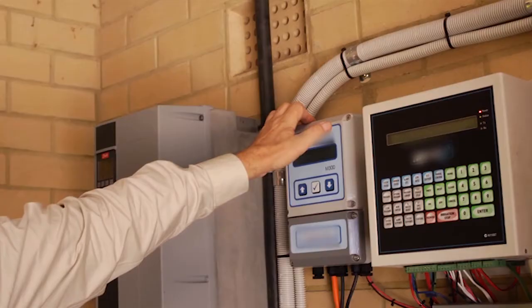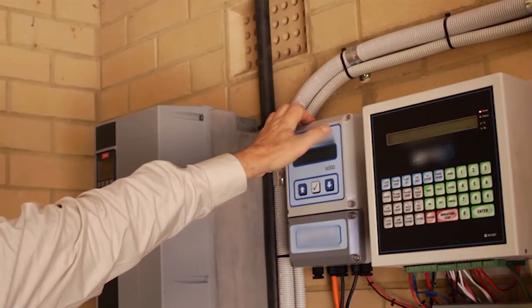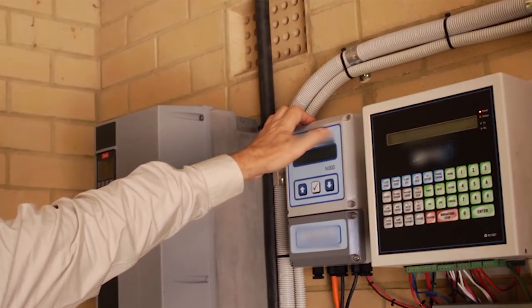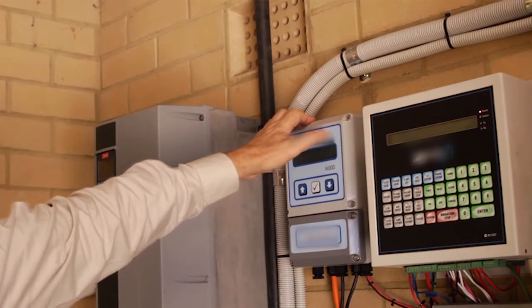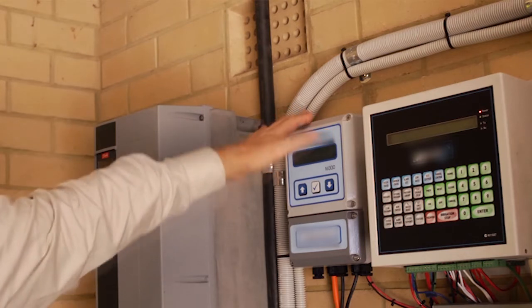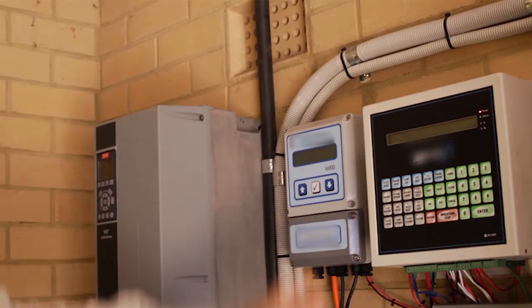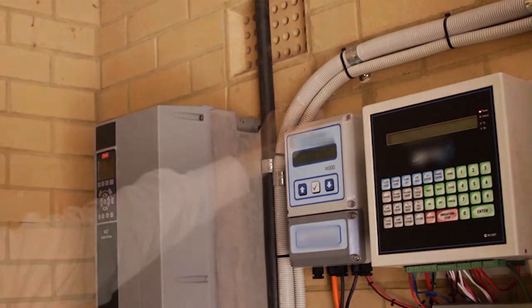So we're in the pump shed, and before we turn the pumps on to start the sprinkler test, we would take a reading of the flow meter. So we have a start reading of the flow meter before we start running the pumps, and then we run the test in the field, and that might run for 10 minutes or 15 minutes. Today we're going to run it for 15 minutes, and then after the test we'll come back and read the flow on the meter and see how much water the pump has pumped.